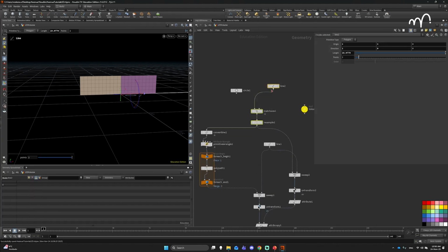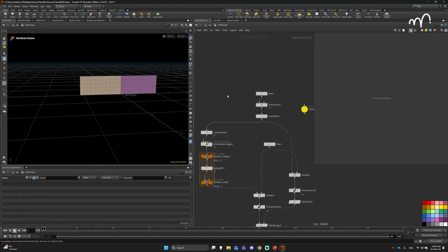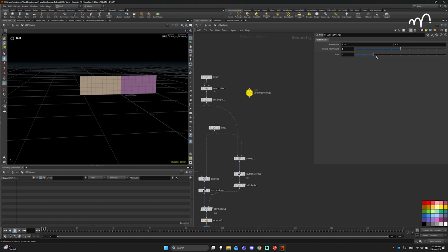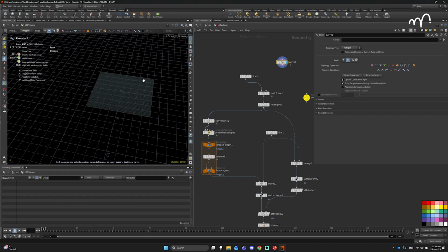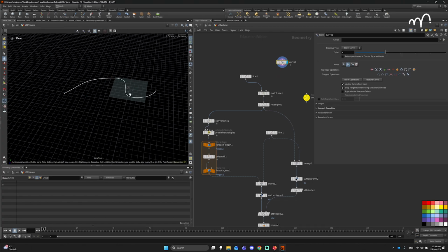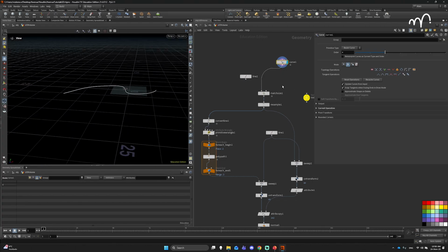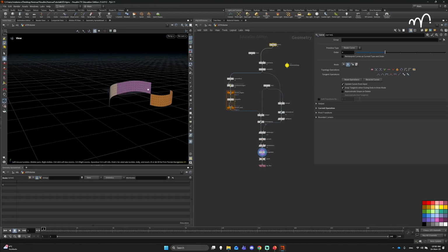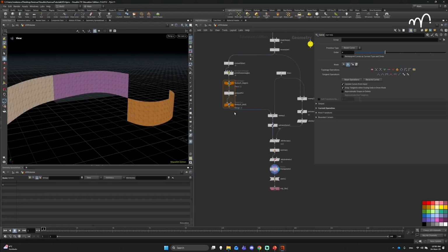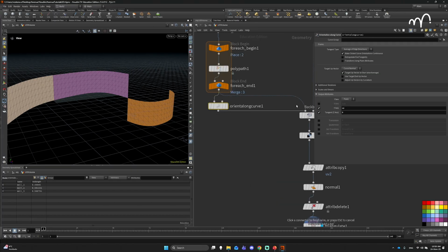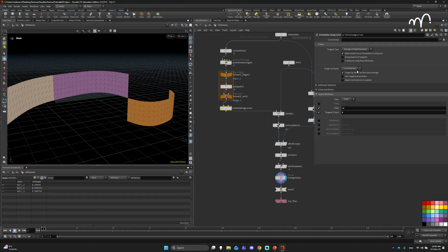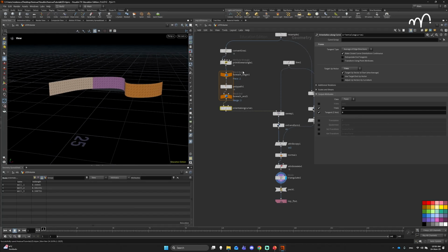So I think the last step now is to import this into Unreal and see how that looks in there. So this works. And the cool thing is we can have now different profiles, and just make a funny one. So Bezier curve. Maybe this one is going to be broken, but that's going to be an easy fix. Yeah, you see here it goes up and down. So we kind of need to do an orient along curve in here, so we get the proper values as the up. So the target up vector needs to be the y-axis, and yeah, there you go, fixed.